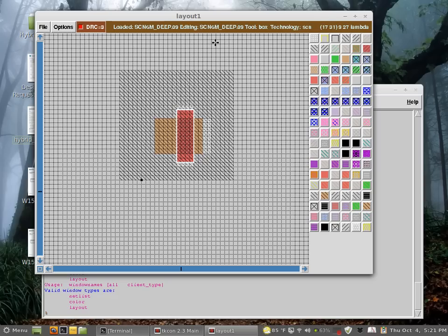What's my channel length here? So it's 360 nanometer. So this is wrong. What I need is 180 nanometer. So I press U to undo. That will undo. And then I do it like that.